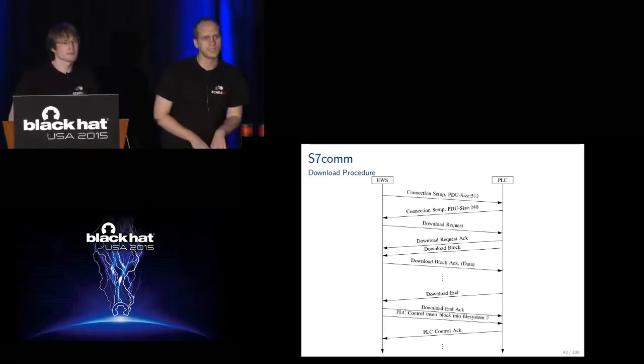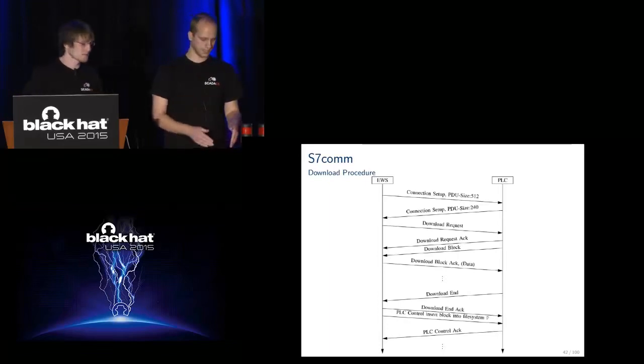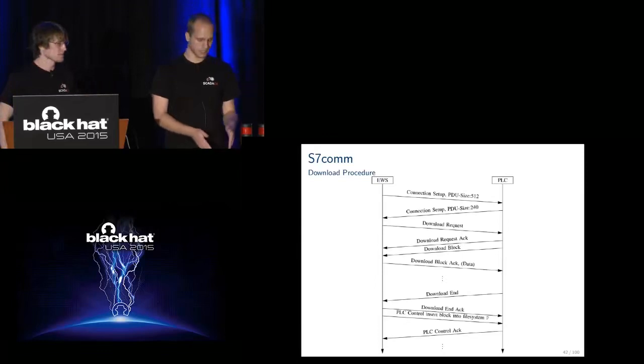Is PLC inject exploiting a vulnerability, or is it just using what the PLC accepts? It's not exploiting a vulnerability. This device is vulnerable in that the protection is just a proprietary protocol. If you know the protocol, you can download and upload code. You're using the normal functions provided by the PLC. We are now able to understand the protocol, and that's why we can do this. It's like in the 90s where we have no authentication or encryption, and it's the same here. So it's not a vulnerability, it's a feature.